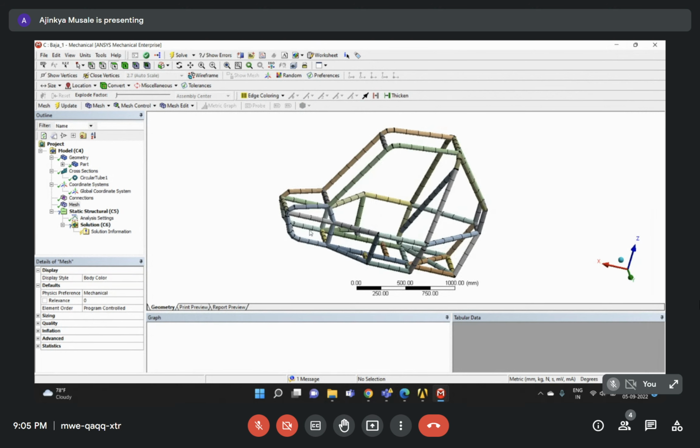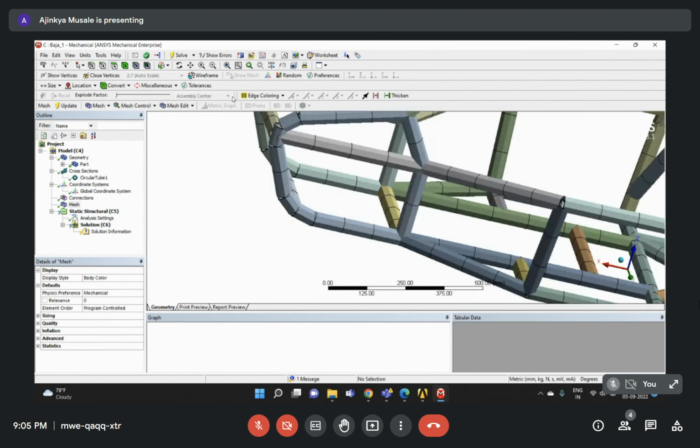I will show you how you can select. Maybe just go to here. Here we have seen we have vertex selection, line selection, face selection, and body selection. So all these options we have seen. Here we have some more options: node selection, and second is element selection. For node selection, you can simply hit the shortcut Control and N. So you can go into that menu directly, and you can select basically any node wherever your cursor goes.